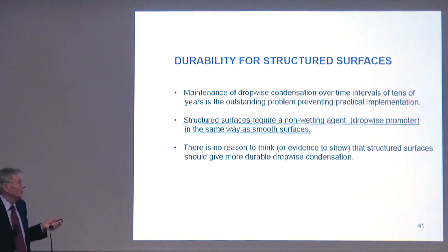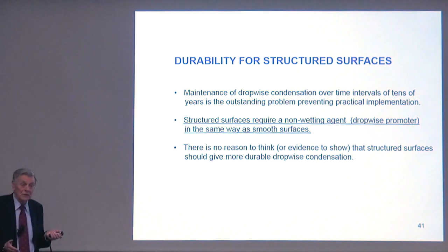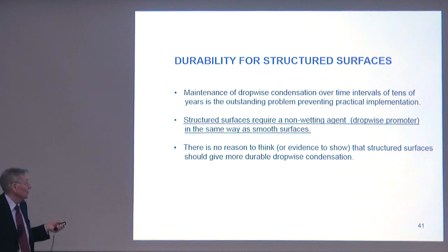Now, looking at durability. This, as I said, is the main outstanding problem in dropwise condensation. Structured surfaces also require a non-wetting agent, which is not always made clear, not to me at least, in the same way as smooth surfaces. So there is no reason to think that the structured surfaces should be any more durable as far as dropwise condensation is concerned than smooth surfaces. There is no reason to think, and so far no evidence to show, that structured surfaces should give more durable